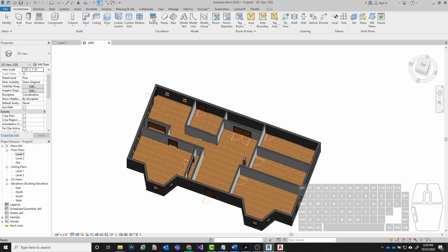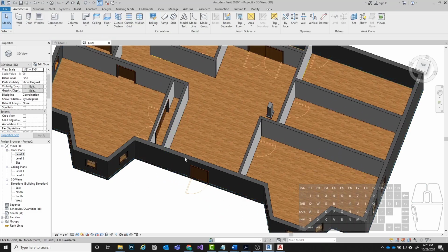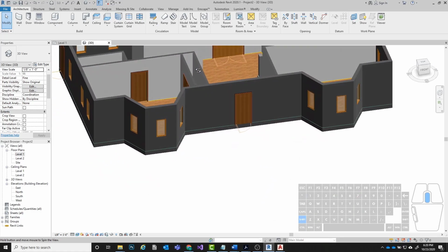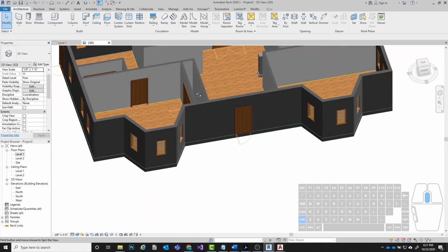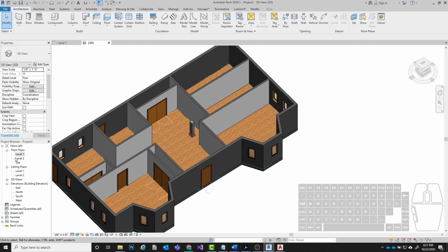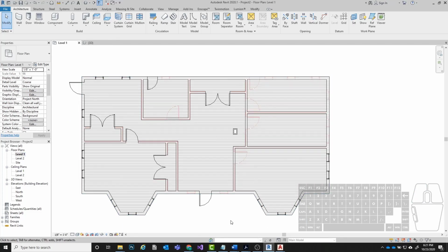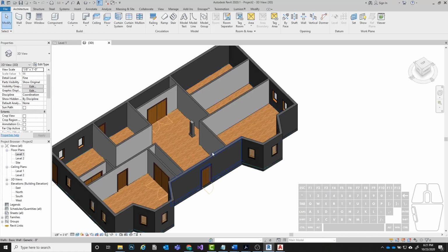That will add in the floor, and then you can confirm that it looks right by going to a 3D view and holding the shift key and middle mouse button and orbiting around. Okay? So that's going to be the lab assignment for this week. Just finish adding in your doors and windows. Make sure you have the clock here, and then make sure you have the floor. I want every single thing that you're seeing here, plus all the extra doors and windows.